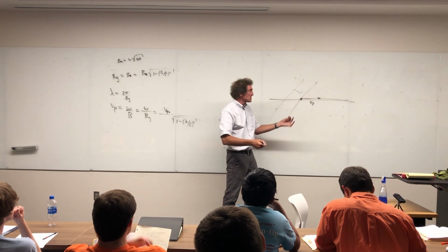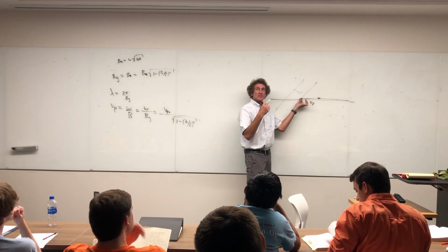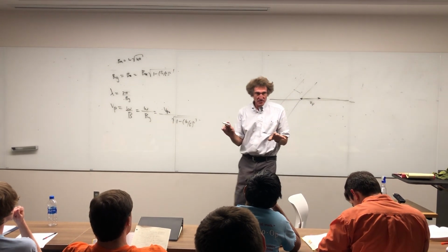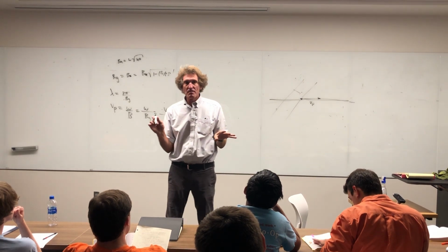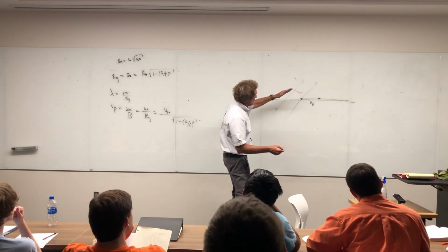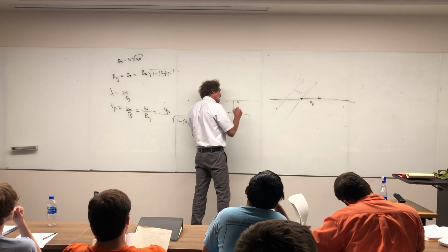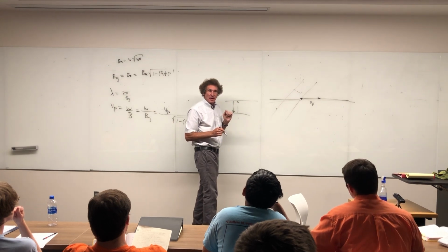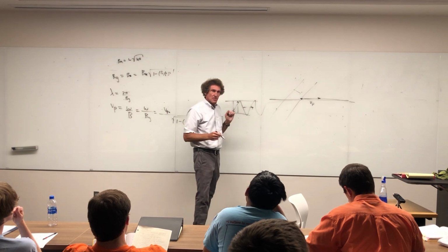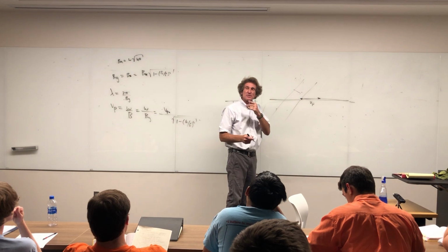Because phase velocity means literally how fast a point on the wave that has the same phase is moving down the guide. It has nothing to do with energy. Well, it does. Do you all follow me on that? How many see that? Now, how fast is real? If you think about it, when waves in a guide are just bouncing up and down, right? Nothing's propagating, right? But if they're bouncing like this, then they have a component of velocity in that direction, right? Well, that's the velocity of energy.